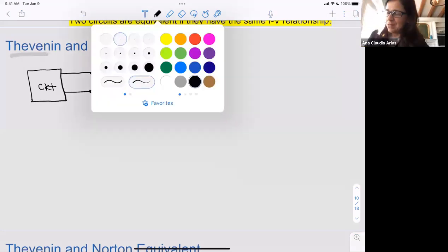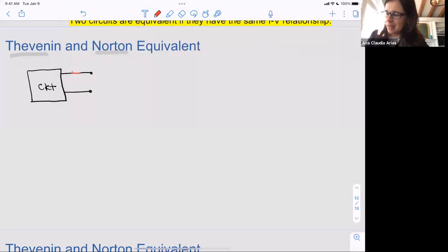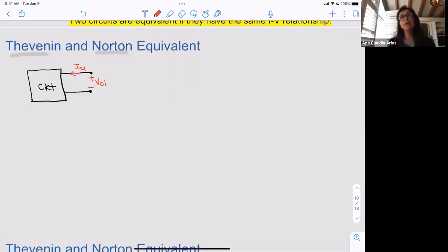And our goal here is always to get I element and V element or V out, because then we can represent other things. Okay, so the methodology here is for you to come up with the simplest circuit possible that you then build equivalences to, or you simplify your model to that equivalent circuit. And we have done this without having this language, right? Where we simplify the array of resistors with our voltage divider. So here we're going to show you the methodology.